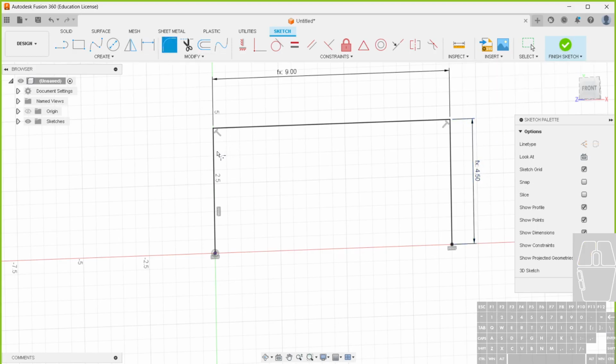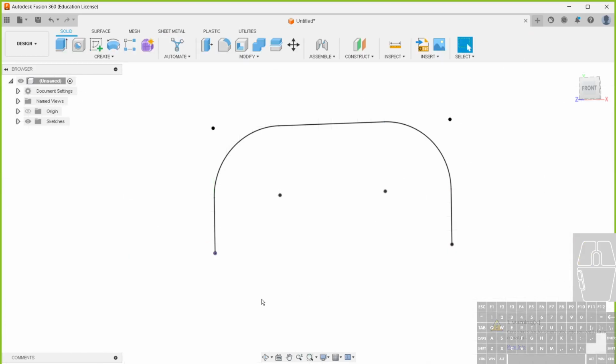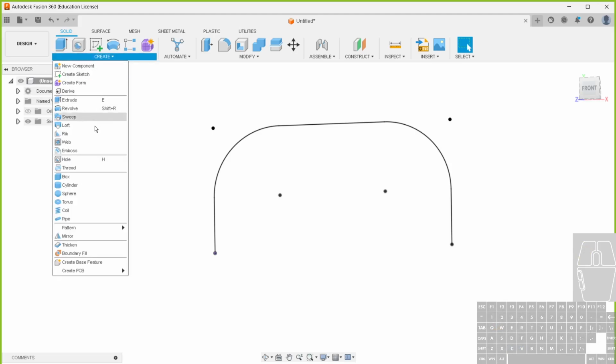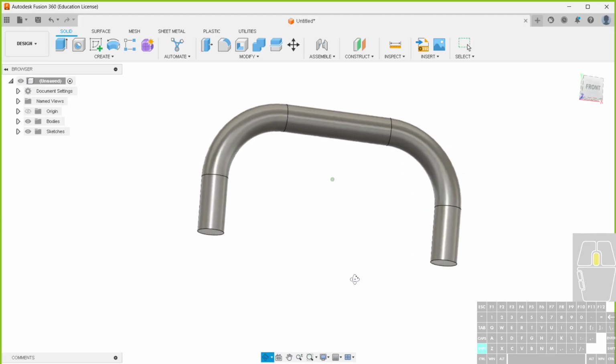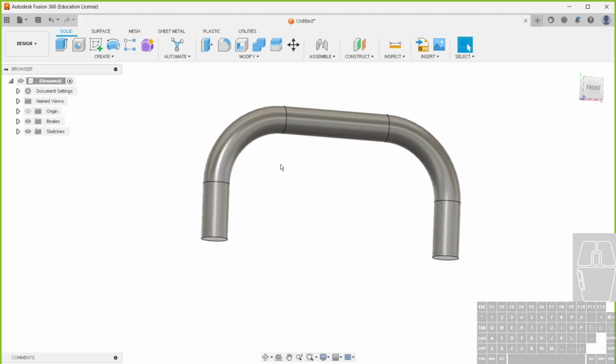And then I need to add my fillets. And this is going to be bend radius. So now when I do my pipe, I got that. Is this only in this part, or will this be in all of it? It's just this one part. So you'll have to redo this again if you start another part? Yeah. But you could just copy that part and then just change your numbers.